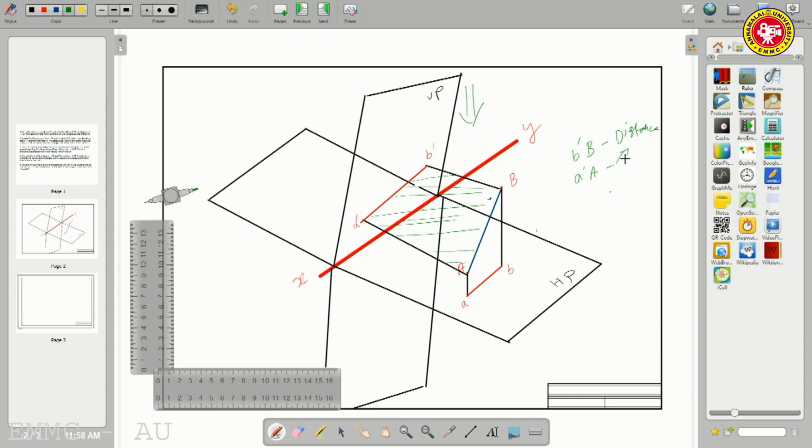So, what about the inclination? What about the inclination of this plane to this line? It is inclined to the vertical plane. Now we are able to determine the apparent inclination and the true inclination, because apparent inclination is for the projection and true inclination is for the true object. Here, the inclination between the planes and the true length, we determine as theta and beta. This is the vertical plane, so we represent it as beta, that is the concept we are following.